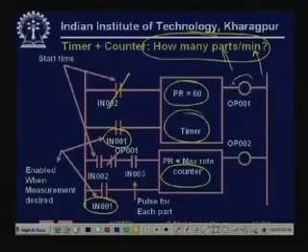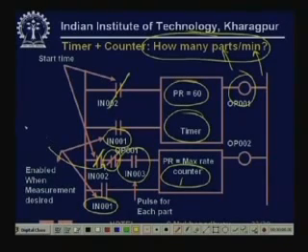So this goes high, and this goes high. Now this does not go high. So this is low. And when this is on, this is also on. So now every time a part arrives, you get a pulse, so the counter goes up. In the meantime, after the time has expired, OP001 goes open, goes off. So this goes to 0, and then further parts are not counted.